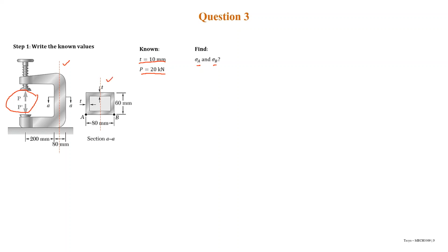Because this neutral axis will change the formula from the usual thing that we know. So make sure that you set the neutral axis in y when the force or the load is acting on the y-axis as well.